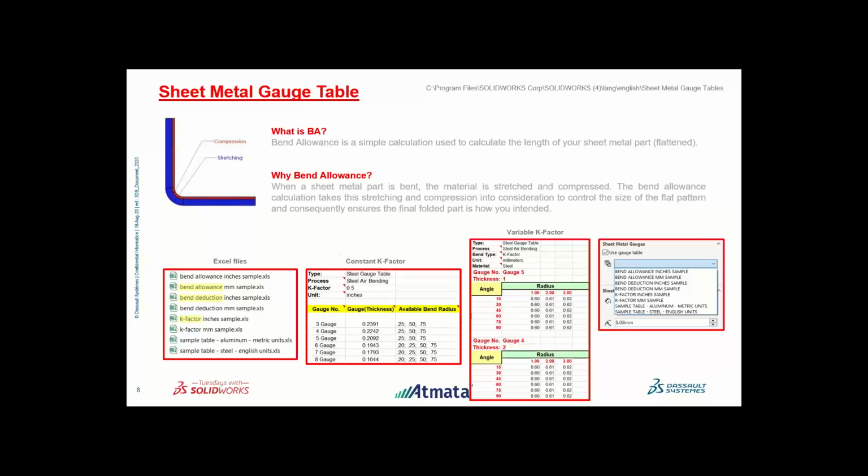One thing to remember here is the bending allowance. I'm not going to talk much about this. Usually we have the bending allowance, bend deductions, and the K factor. As we bend the sheet, the neutral axis is not going to be exactly at the center. Based on the hardness of the sheet, the chemical composition, the physical properties of the sheet, the neutral axis usually changes. And also it's based on thickness.